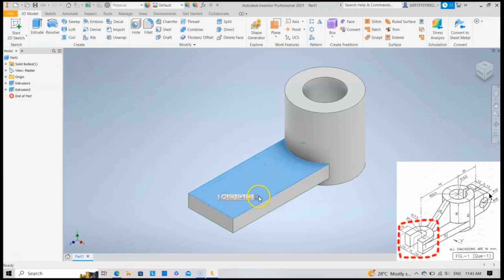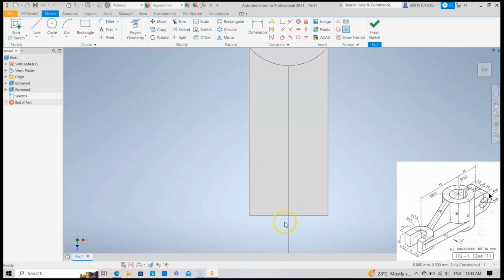To draw the U shape, click Sketch on the upper face of the rectangle. Use two tools, which are Line and Tangent Arc. Draw the shape just like in the sketch freely, then put the dimension.